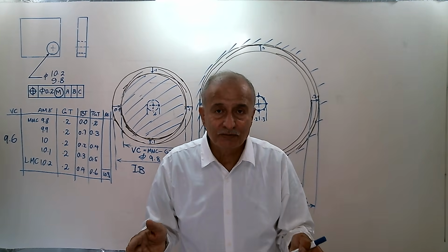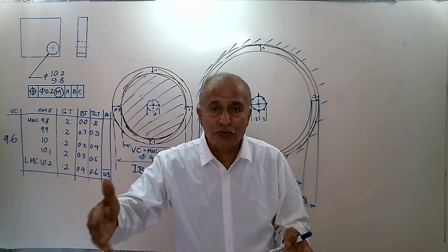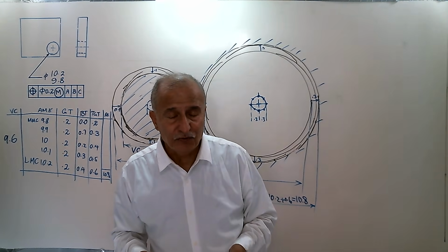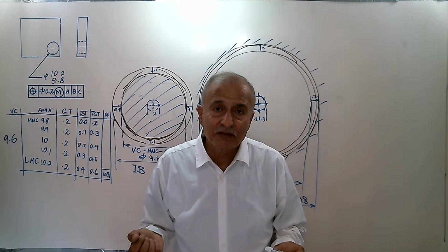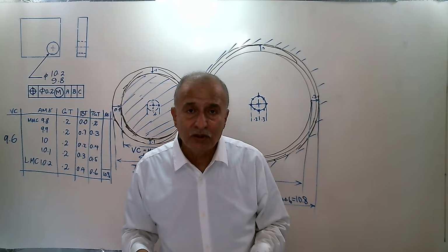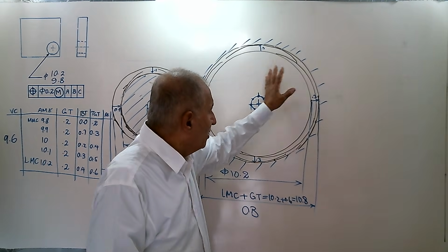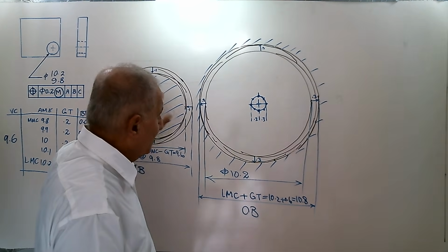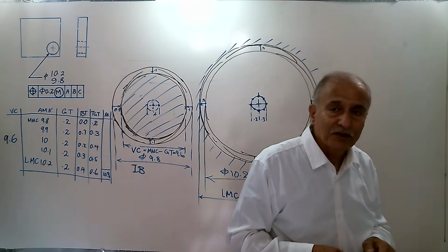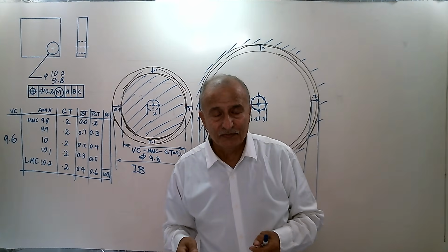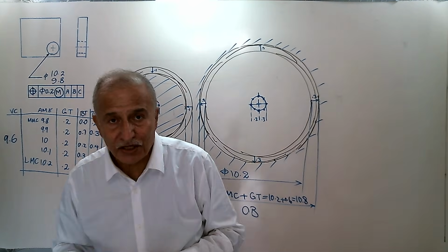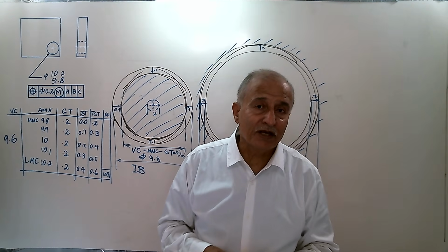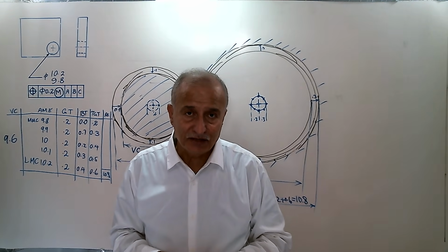It depends on the part, at which size it is produced. Then you must consider all possibilities. If you produce 1 million of this part, consider all of the cases. All this region may actually be taken by the different holes. Okay? This is why we need inner boundary, we need outer boundary, and virtual conditions, which plays the role of inner boundary in this case.